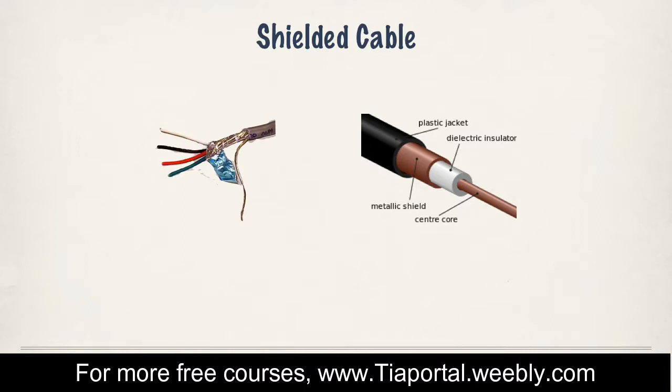This is something you'd see in something called RG59, which is a high grade, a very high quality cable used in, for example, broadcast television and coaxial TV, running the cable TV signal to your home and around your home and into your home, etc. And so there's one. You can see the center core. That's one conductor cable. Around that, there's what they call the dielectric insulator. Usually, you can see the white color is like a plastic. And again, that is a very poor conductor. So the electricity stays in the center where it travels smoothly and doesn't like to get out. Wrapped around that is a metallic shield, and that can be a variety of different materials.